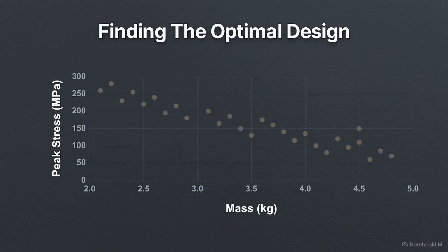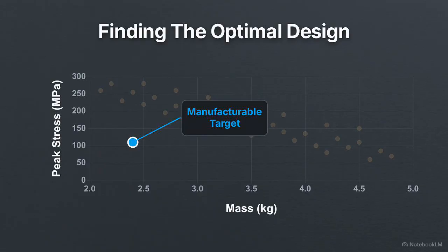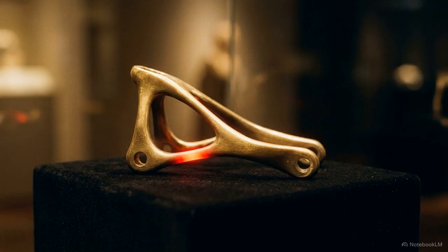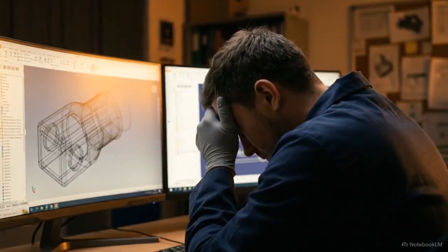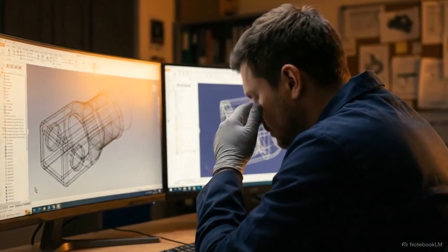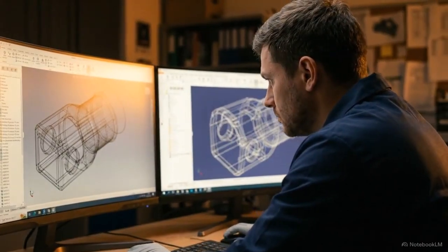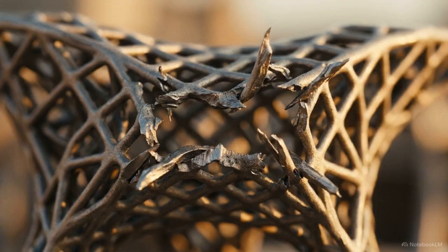It provides an analytical trail where engineers evaluate columns of mass and peak stress values across dozens of iterations, manually hunting for the specific candidate that balances safety, manufacturability, and lowest weight. Trusting a pretty skeletal result without double-checking the underlying assumptions is dangerous. If the human engineer misses a critical load case or sets a factor of safety too low in the initial setup, the software will generate a structure that is unsafe in the field.